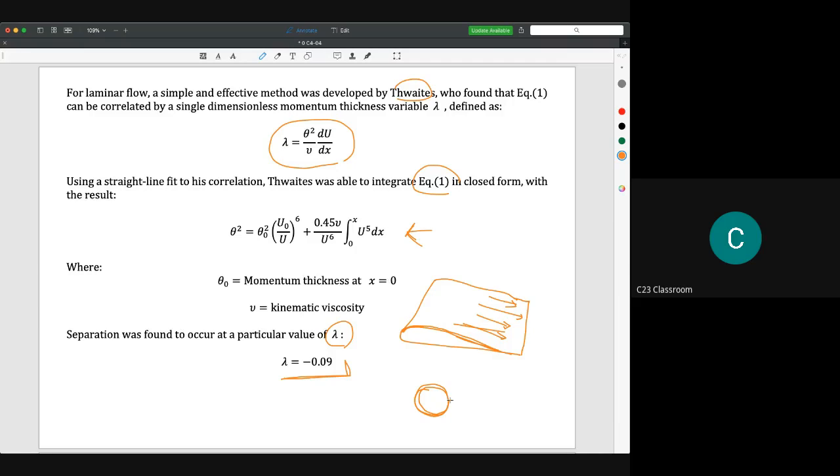What is the difference between flow on the aerofoil like this one? As I said, it will create a boundary layer like this. It starts from here and creates a boundary layer here, and it is still in 2D. We just evaluate the x here, for example, and this is x, and all of this becomes y, because normally the changes in z can be neglected. So it is still a 2D or planar surface.